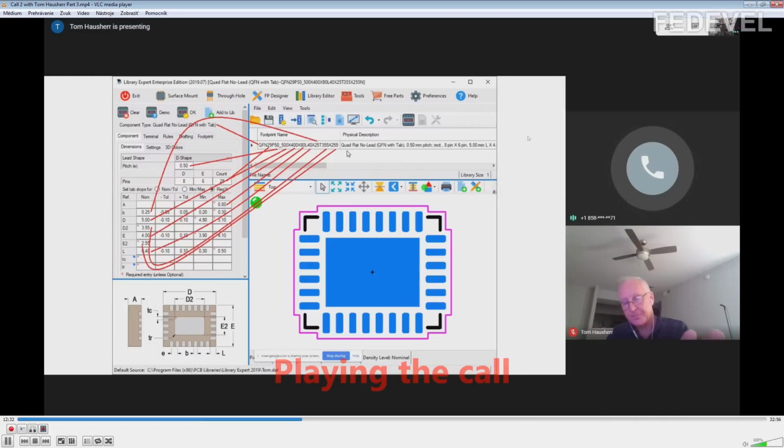I'm just saying that we're getting a lot of feedback from a lot of customers that the IPC 7351 name for footprints for land patterns is too long, and the names that they're going to work on right now are JEDEC, and they're even longer, and they hardly make any sense. The JEDEC naming convention is very, very difficult to understand. You have to be almost a rocket scientist, or have a little cheat sheet to know what each character in the name is.